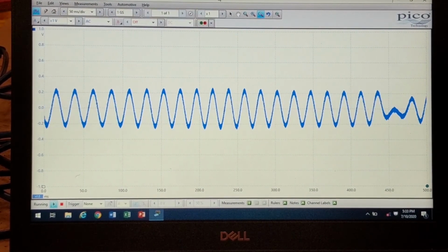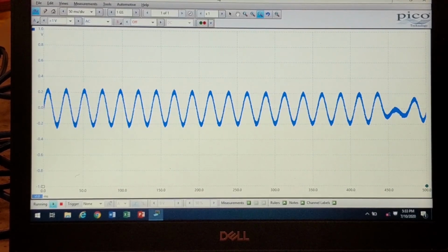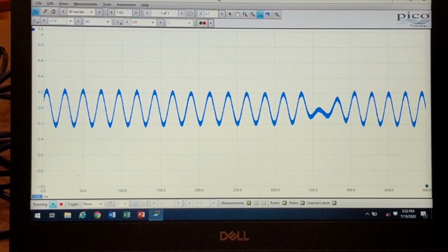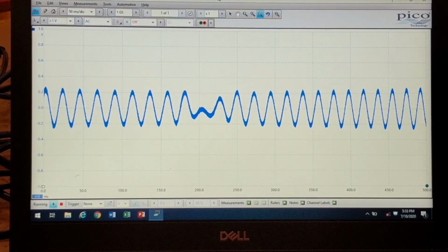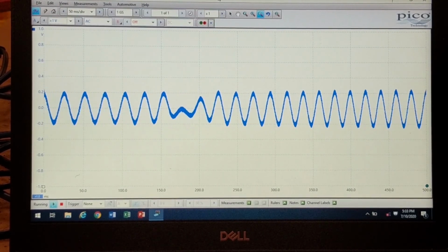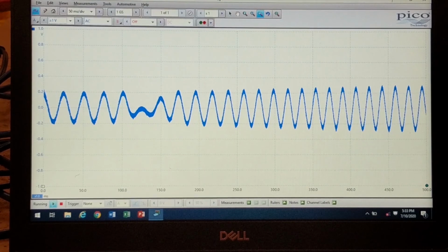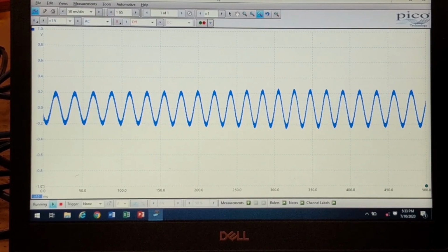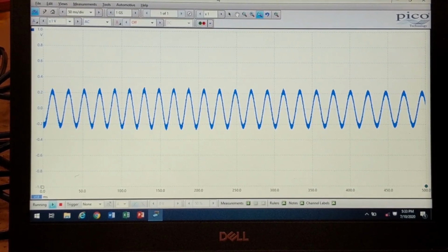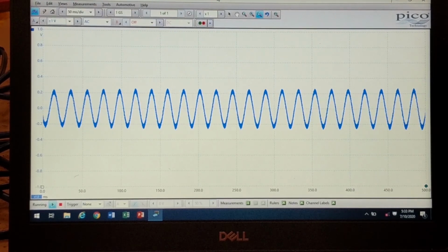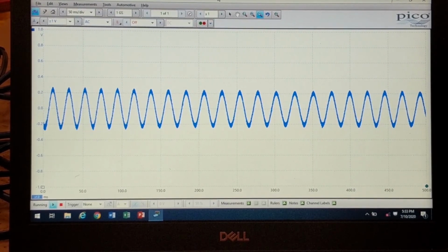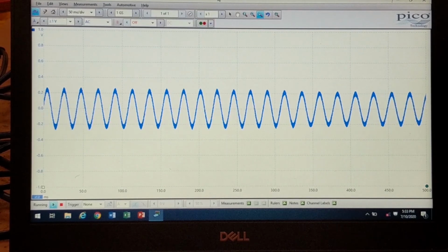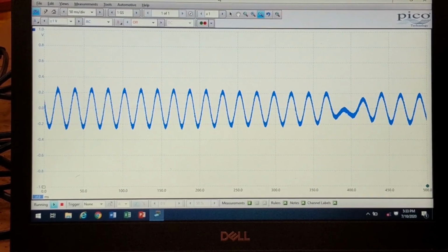It's a sine wave. As each tooth approaches and passes and moves away from the magnetic field, we have an analog signal that shows its relative position to the magnetic field. This is inducing a voltage. In one direction, it is producing positive voltage, and the other way, it is producing a negative voltage. So we have alternating current.